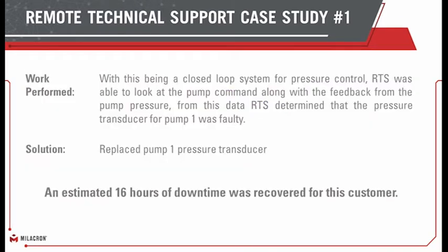With our technicians' knowledge, combining not only themselves on the phone but our experience in the shop and some of the experience around them, we were able to look through the hydraulic circuit and identify some potential areas, work with the customer to eliminate a few things, and very quickly get that down to a transducer issue with the system and the setup. With this particular solution, luckily the customer had a machine that they were swapping a mold on that they didn't need for a couple days, so they were able to take a similar transducer part number off of that machine, put it onto this machine, and get the machine back up and running very quickly.